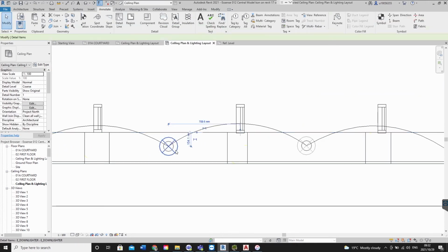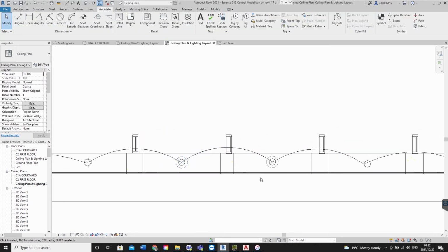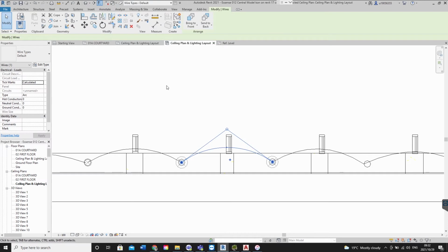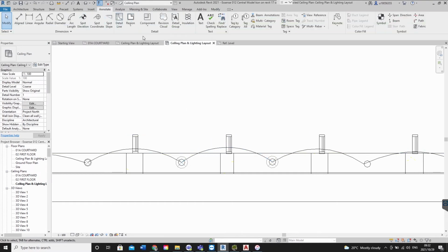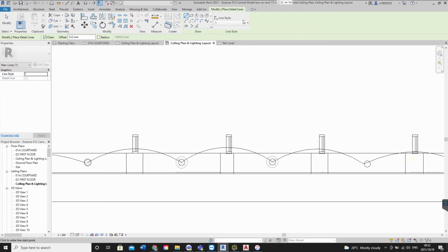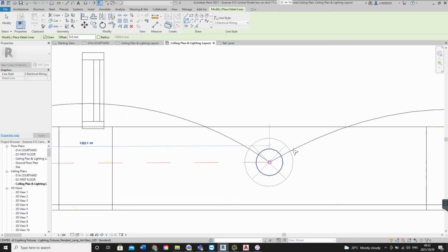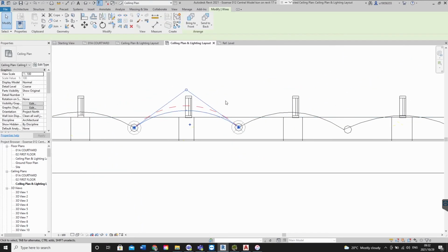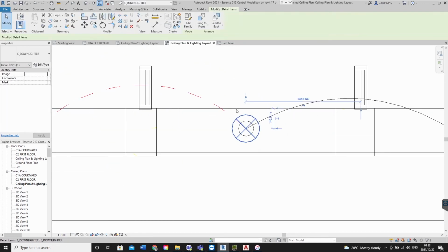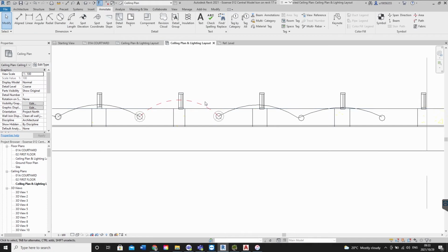Now what's neat is, this is technically a symbol, but this is what I would recommend you guys do, so it doesn't have that complexity. Okay, what is this thing again? This is a default wire. Okay, so now, instead of using electrical, you go to detail lines. There is an electrical line here already. Just go and see electrical fittings. Oh, no, electrical wiring. And you can change this in the project, snap center. Get rid of that. So technically now this is an electrical symbol and this is an electrical line that you can manage like you would in AutoCAD.